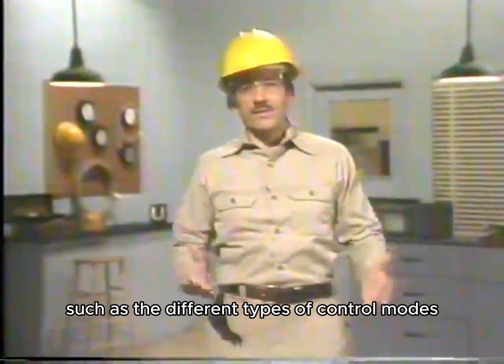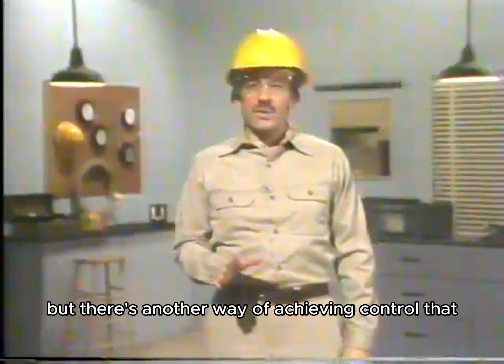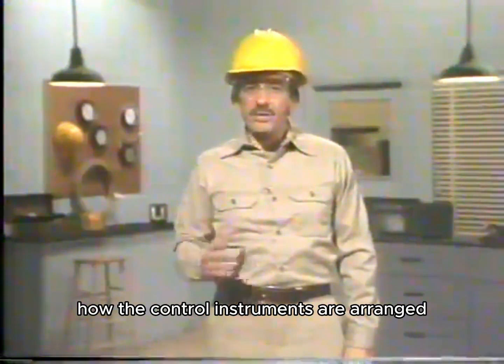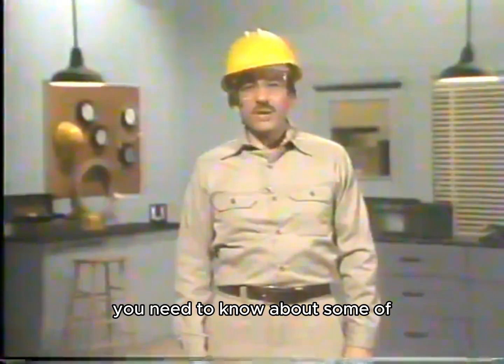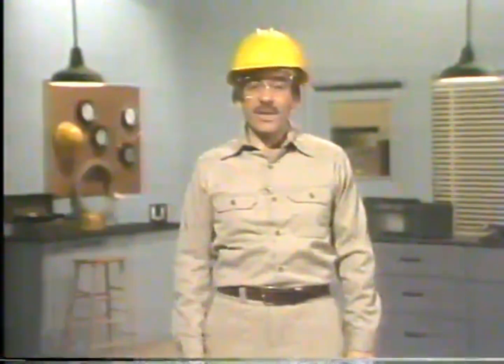Now, some of these you should already be familiar with, such as the different types of control modes, like proportional, reset, and rate. But there's another way of achieving control that, combined with the different control modes, works to make control more effective. This other way of achieving control has to do with how the control instruments are arranged. And as instrument technicians, you need to know about some of the basic control arrangements if you're to be able to adjust and maintain the control systems in your plant.